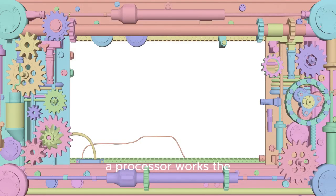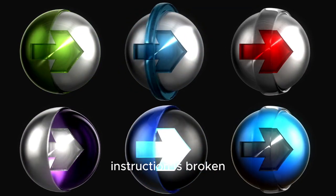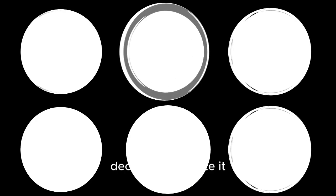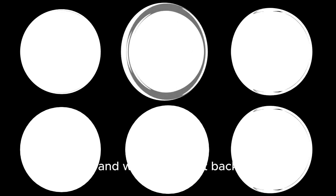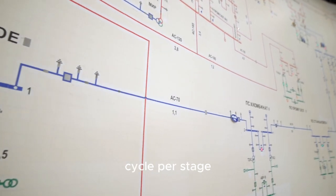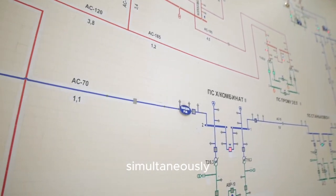Pipelining in a processor works the exact same way. The execution of a single instruction is broken down into simple stages. Fetch the instruction, decode it, execute it, and write the result back. Because each instruction is simple and takes one clock cycle per stage, the processor can have multiple instructions in the pipeline simultaneously.